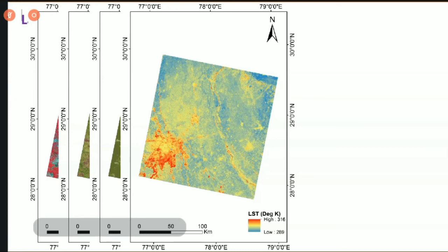Here we use a Landsat 8 image and the time of acquisition is around 10:48, so at that time your LST is always higher than air temperature. You can cross-check your data sets this way to see whether your analysis is okay, and check your results in an iterative manner.